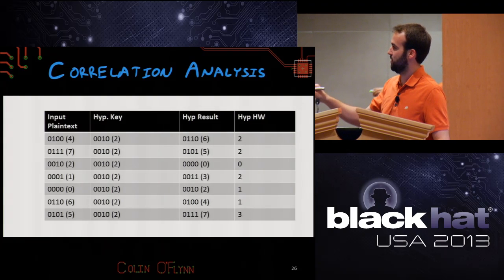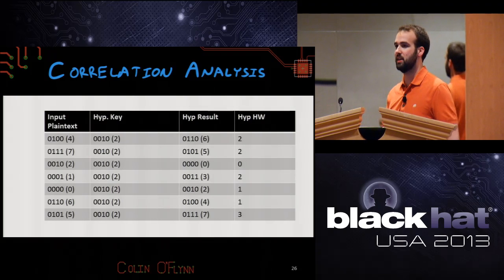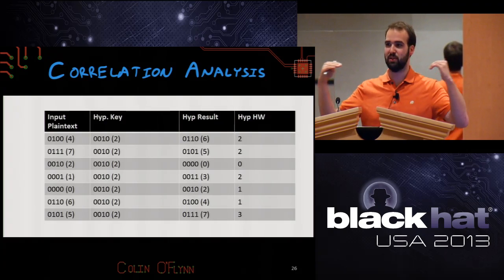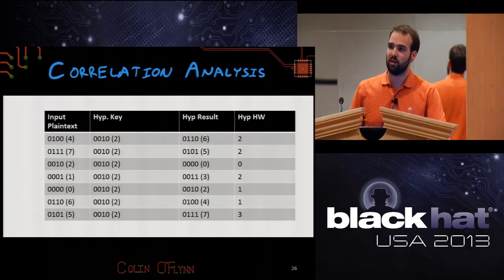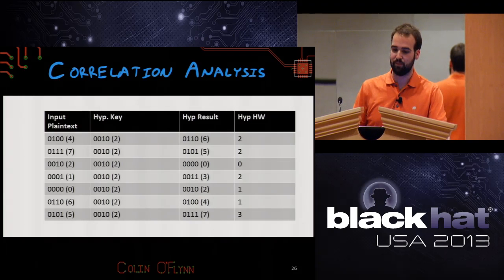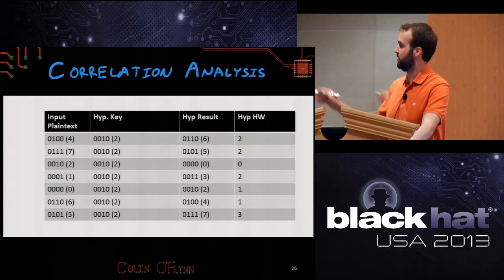And why I have so many traces, here I have 7. In real life, I was showing 50, it might be thousands, is that over time, everything else becomes noise. Everything else just becomes white noise and effectively goes to 0 when you're looking at the correlation, but the data you care about, even though it may only be 8 bits out of 128, creates this huge spike.